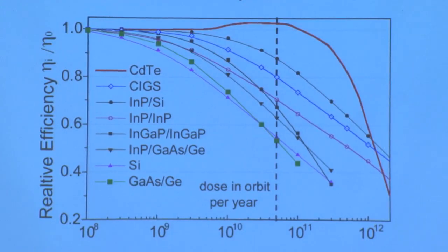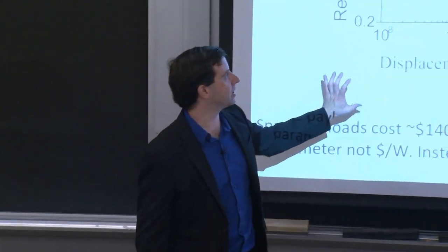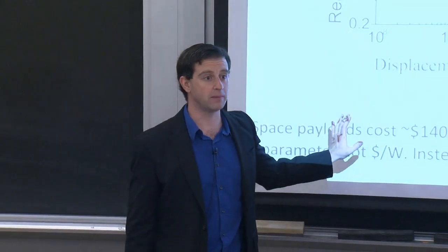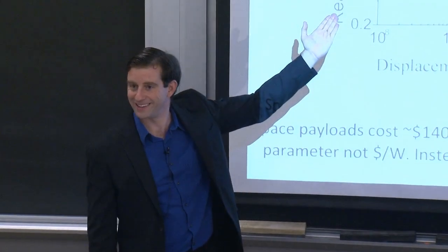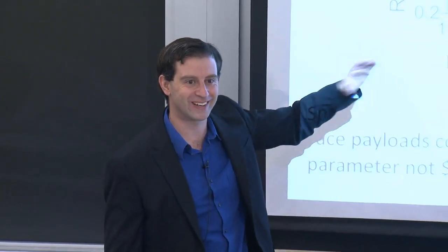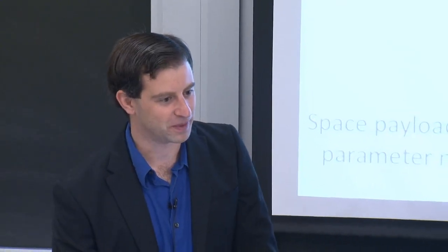So we have the radiation hardness to take into account if we're putting these solar panels out there into outer space. This is one older study. I would definitely encourage you to look. There may be some newer studies. As the solar cell efficiency improves, they become more sensitive, right? Because you begin decreasing your efficiency with smaller variations in the minority carrier diffusion length. So those charts might look a little different as time goes by.